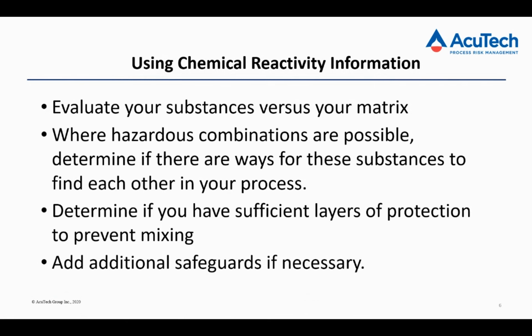If you don't, then your risk matrix will give you some prioritization for deciding what you need to add as far as additional safeguards to get where you feel safe enough on that interaction of chemicals. And if you bring a new chemical into your site, you should certainly go through any potential reactivity issues. You might have a line on your management of change forms to make sure that you've looked at potential interaction issues if you're bringing a new chemical on site.